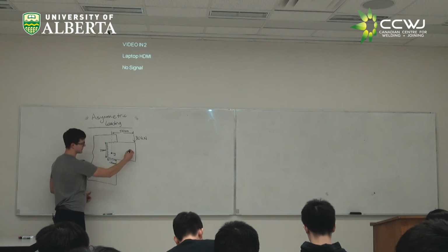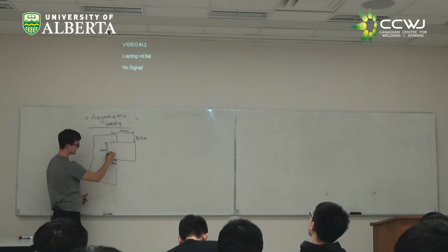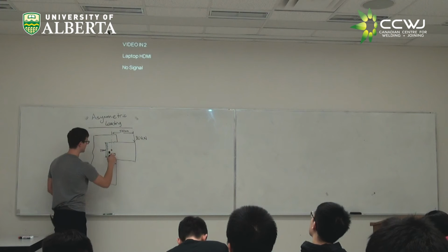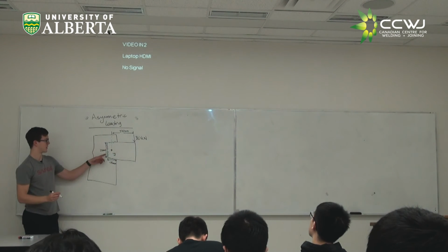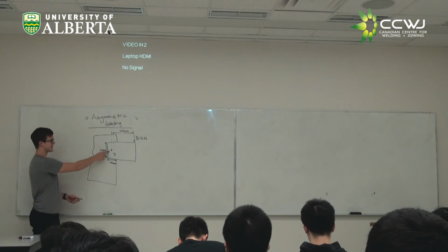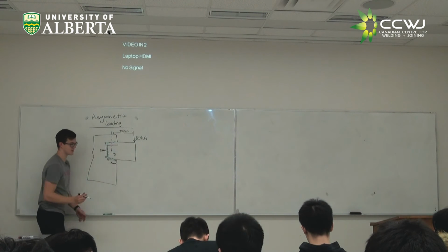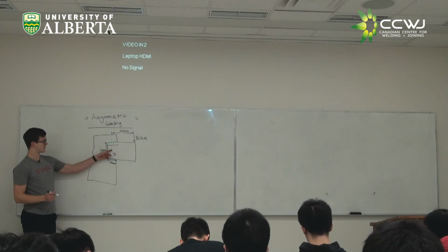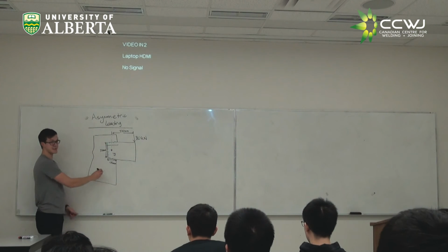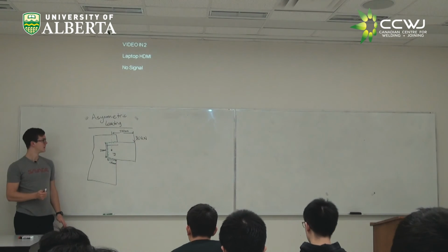So if we had a load that was just applied through the center of this, sorry, I'll draw it properly. This is the center of gravity of our weld system. Does everyone see how that would be the center of gravity? We're going to calculate exactly what this length is and what this length is in a minute. But if we calculate the center of gravity of our welds, and we were to pull through that center of gravity, this problem would be exactly the same as we were dealing with before.